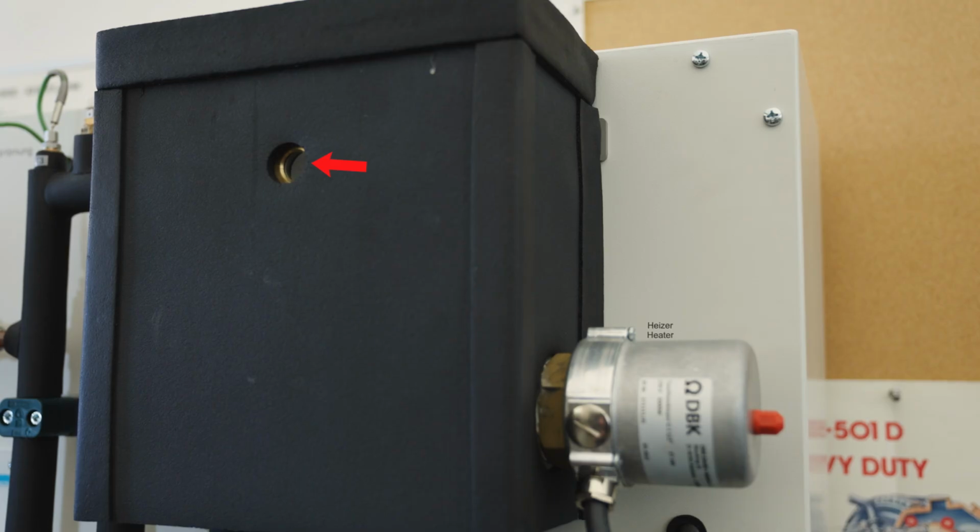Before operating the machine, make sure to wear safety goggles, adhere to the laboratory safety rules, and ensure the hot water tank is appropriately filled by checking the level through the seeing window. Filling the tank with water is typically performed by the TA. We are now ready to begin turning on the machine.